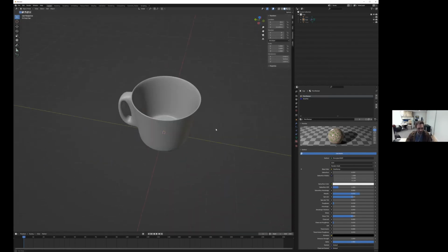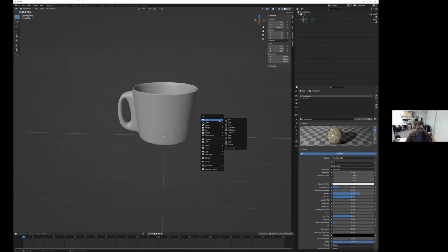The first thing you must do is add a domain. Now, a domain is essentially a bounding box that serves as the boundary of the simulation. All the fluid objects must remain in the domain. That's important. So if you don't have a domain, your fluid is not going to work. Fluid objects outside of the domain will not bake, and you won't see anything. So as long as the fluid or any of the simulations is within the bounding box, you should be able to see it. So with that being said, how do I add a domain?